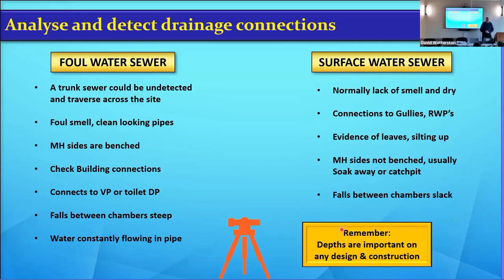generally a trunk sewer, which is foul water, will be flowing all the time, because somebody somewhere along the road will be flushing a toilet, emptying a bath, emptying a dishwater sink, or whatever. If you pick up the manhole, you probably won't be doing it because again, health and safety cover. The surveyors will do it. But if they're unsure, you can have a wee look down it, and if it's flowing, then it's generally foul.